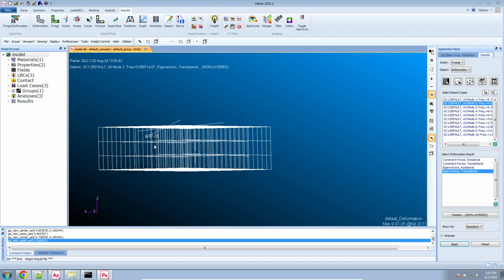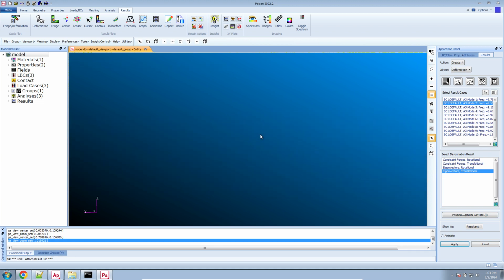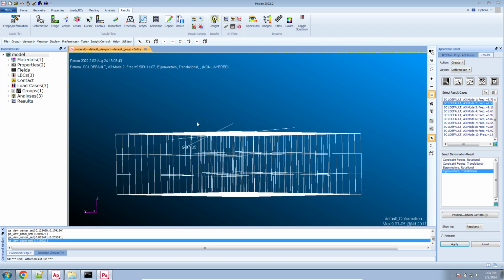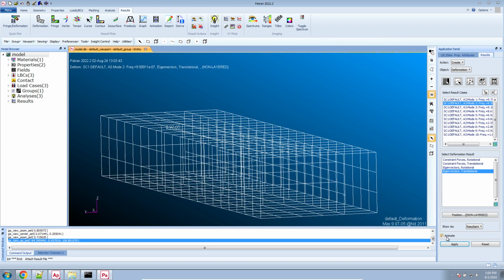It will also tell you if your mesh is properly supported. So that's why I'm recommending that you perform a normal modes analysis. First, make sure everything is connected to each other properly. Then after that's okay, perform a statics analysis. So here, let's go ahead and fix this.